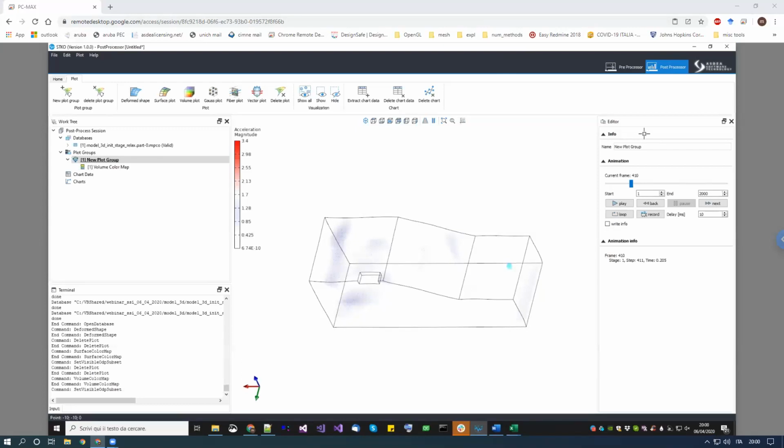So the soil material is nonlinear. We still use an elastic material for the free field soil column. Actually, I didn't see any reference on this, but I think we should use the same nonlinear model. I'm pretty sure about this, but probably in the next webinar, since I want to do the same analysis with nonlinear materials and a superstructure, we can investigate this topic. But yes, I'm pretty sure it should be the same one.